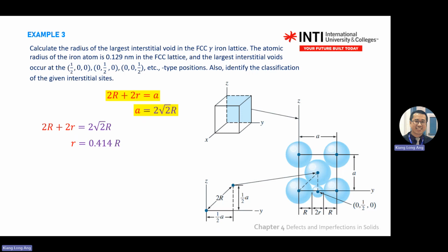It cannot be bigger, because this is the size that it can fit in the host, of the R of the radius. So from the table you find. It's not saying that the replacement cannot surpass 41 or not smaller than 41. No, this is not substitution. This is you inject an alien atom inside there. It's not replaced. This is not Hume-Rothery rules. This is interstitial.